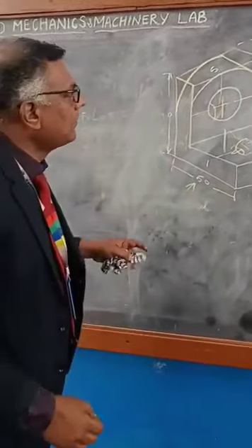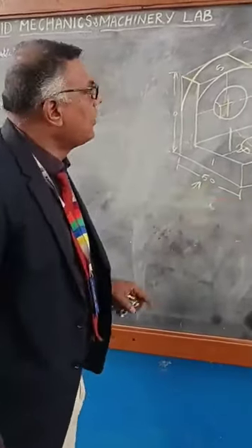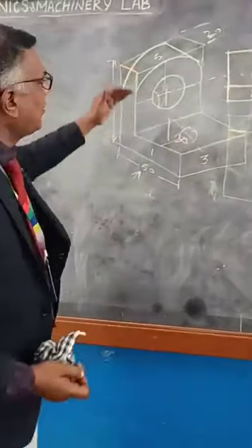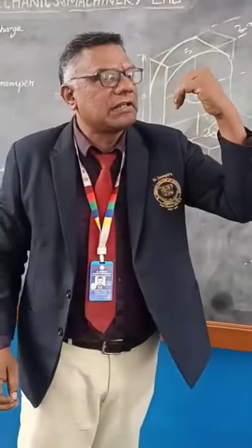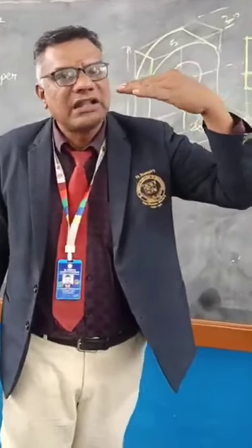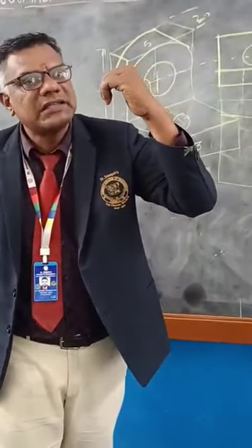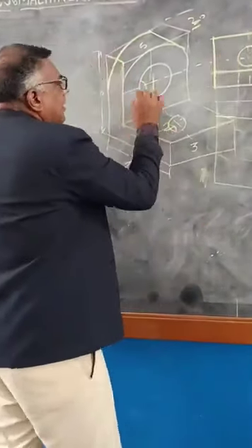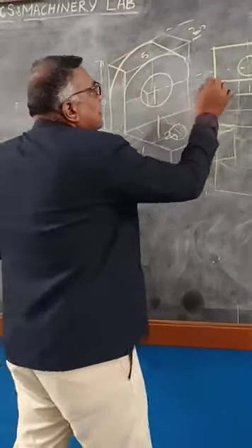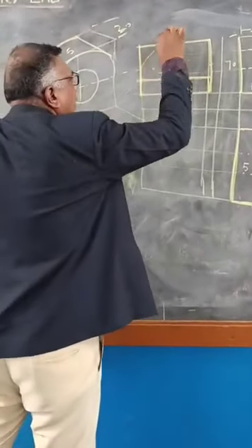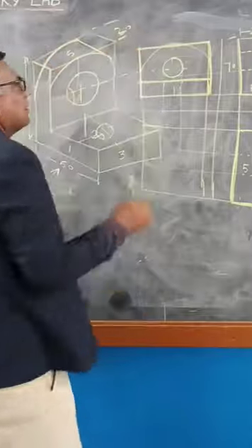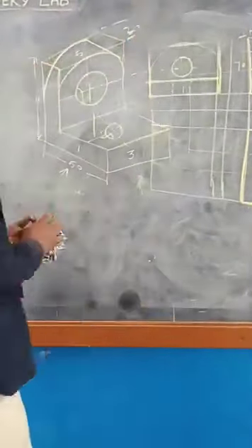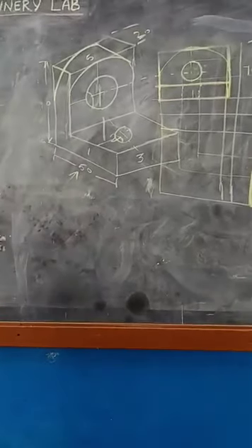So what will happen here now? When you are viewing from this side view, previously we made a rectangular part. Now it is like this. Previously it was a horizontal line. Now it is a semicircle line. For that, for any diagram there should be a center. From the center, draw an arc. So you just rub this side. Any other thing is the same.